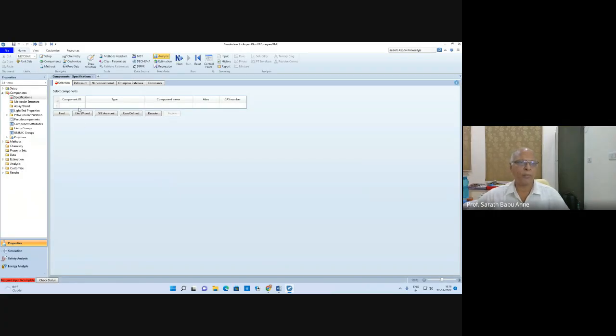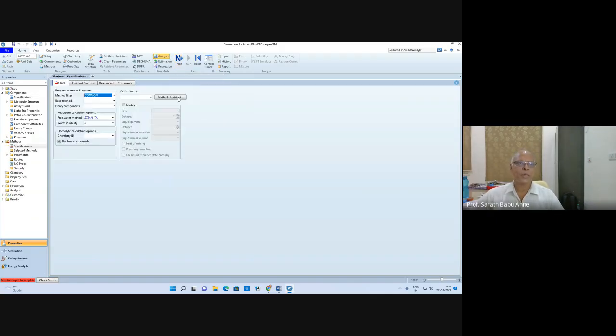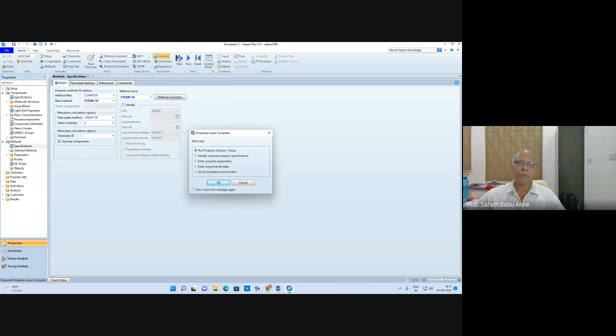So usually the first step in process simulation is to define all the components involved in your problem. Obviously in this problem, we have only one component that is being handled, which is water. After defining the components involved in the problem, you can go to the next input screen by pressing N. The second step is to choose a property model. You can see there are several property models available in Aspen, but in case of water or steam, the best bet is to use steam tables as the property model. Having chosen the property model, now you can go to the next input step by pressing N.